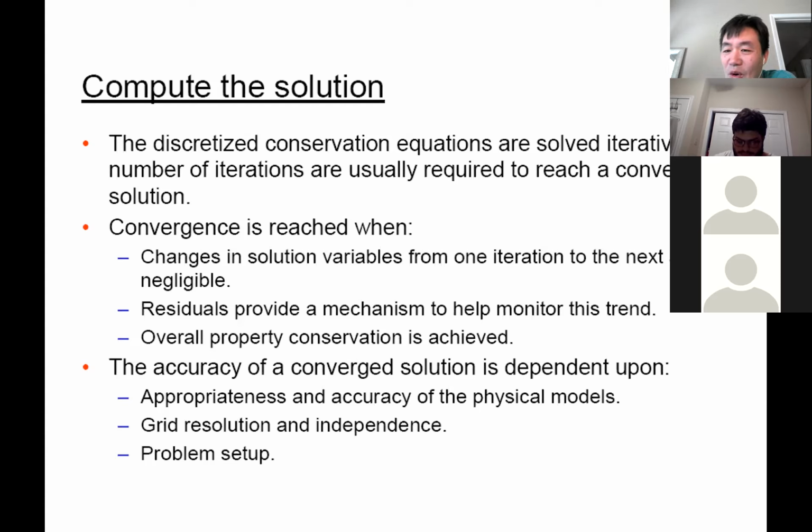So you have to determine if the result is reasonable, and you have to verify and validate your result with existing data, with measurement data, with experiments, with existing literature data, or with a theoretical calculation. You have to make sure your result is not just a color picture.